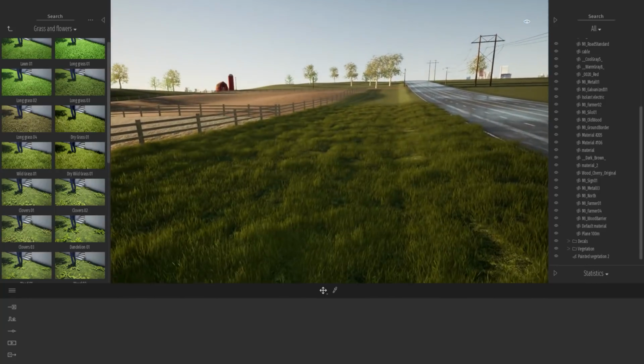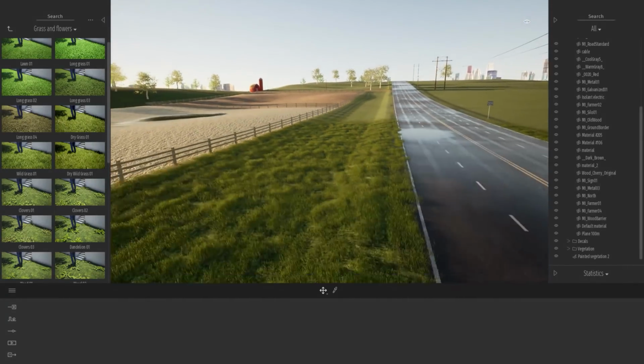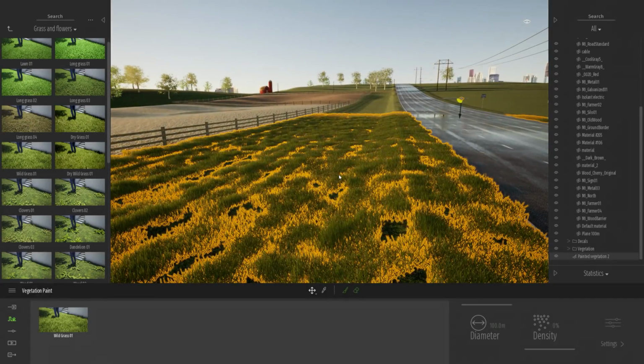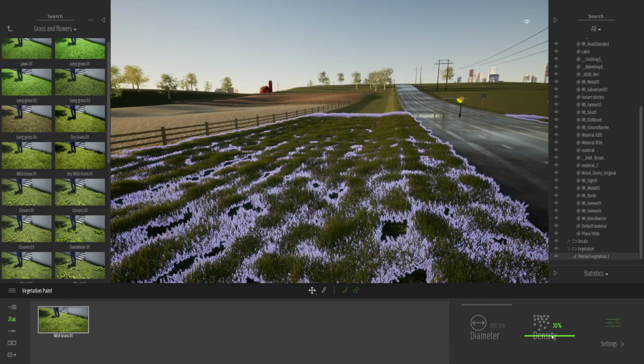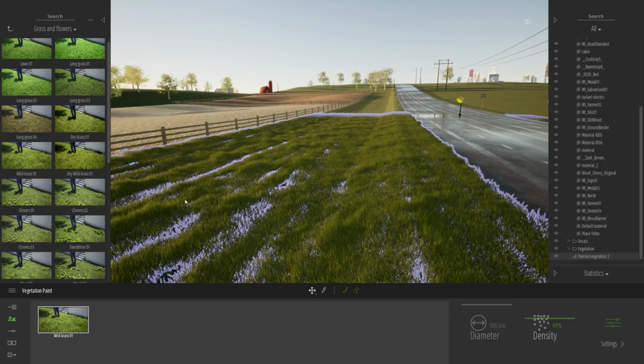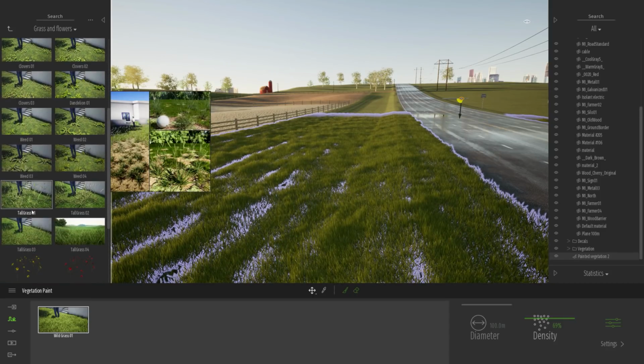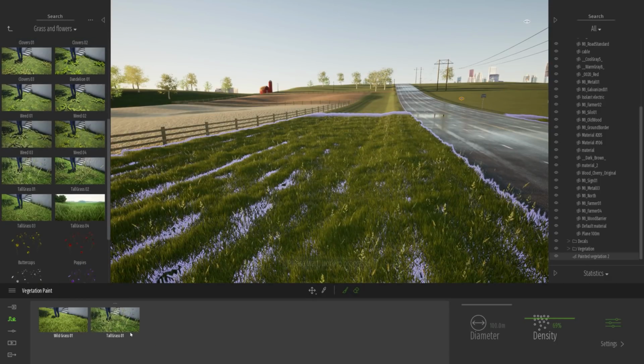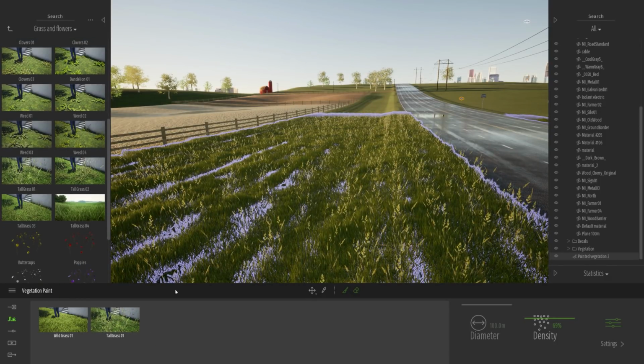In this new version of Twinmotion, the painted elements, the painted grass, the painted layers exist in the scene organizer. It has an eye that you can turn on and off, and you can also change the density after you painted the object. So for example here, if I select my grass, I can raise the grass density. I can even add more objects to this existing layer. So for example here I can add some tall grass that will be scattered all around this layer. I don't need to paint it anymore, it's scattered automatically. Let me just lower the density a bit of this tall grass.